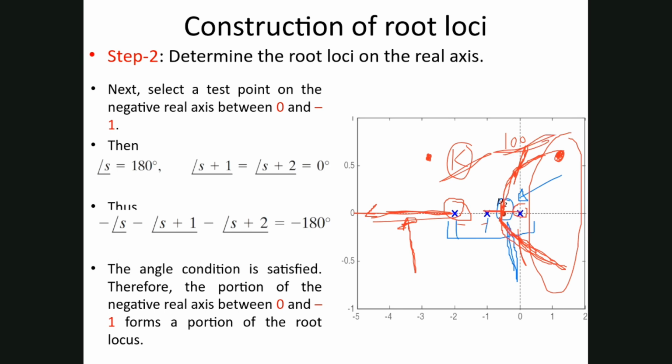So if you're having this kind of a root locus for any given example, guess what? Up to the value of k 100, your system is stable. As you are increasing the value of k to more than 100, your system will become unstable, because your two poles are entering the positive half of the S-plane, or the right hand side of the S-plane. This is just an example. Okay, this we need to check through the root locus method.